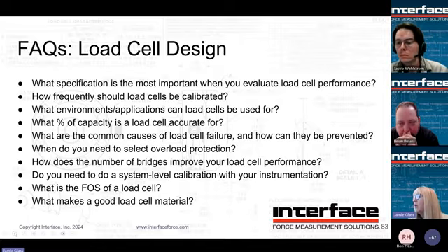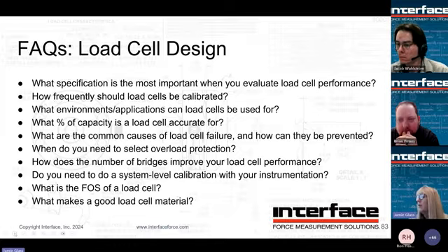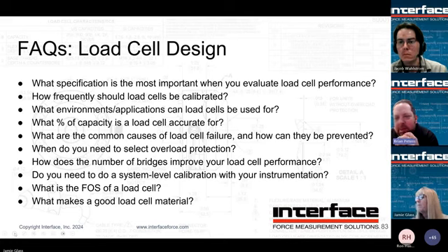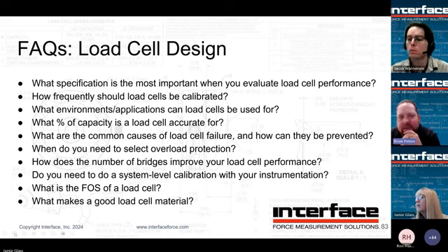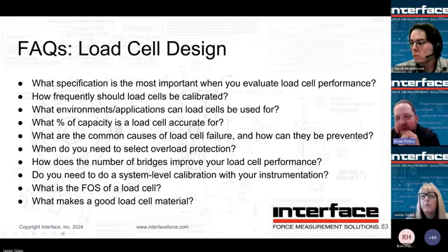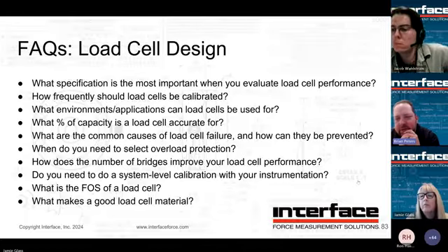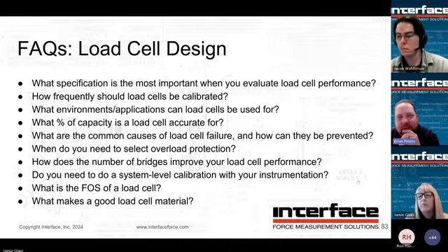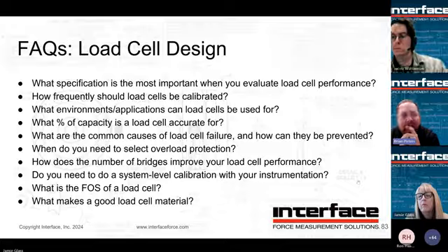One question: I noticed that my zero reading is drifting every time the load cell experiences a temperature cycle, 170 degrees Celsius. Any comment to that? That would not be typical unless it's in an assembly, where you could have some residual mechanical effects. If you have just a sensor sitting there and it's going through temperature cycles and the zero is changing, that's not typical behavior of a healthy load cell. Would you agree, Jacob?